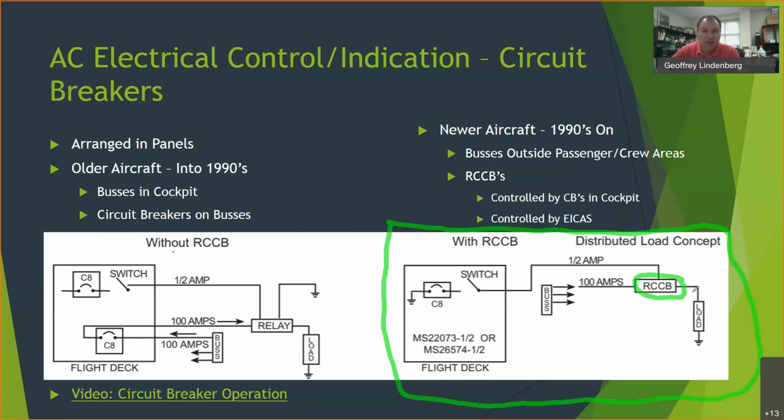Even on the 787, that airplane's gone away from pneumatic systems. It uses electrically heated leading edges for anti-ice, and it uses electric motor-driven environmental control systems, PACs. It doesn't use bleed air at all, so everything's gone electrical on that. And the main loads are down under the floor, away from the passenger cabin, away from the flight deck.